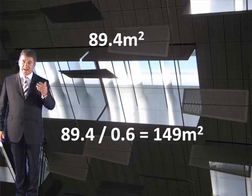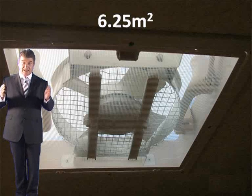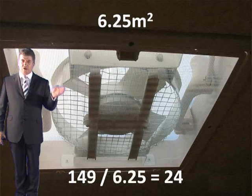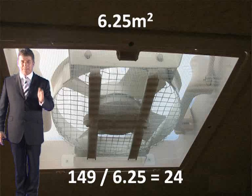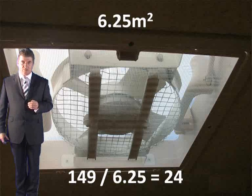Now, don't forget that ventilators don't come bigger than 6.25 square metres. And that's because they can't test them any bigger than that. So they don't come bigger than 6.25. So you divide 149 by 6.25, you get approximately, we're going to need at least 24 ventilators. 24 ventilators, that is the absolute minimum that we need in each reservoir. So where do we locate these ventilators then? Where should we put them?